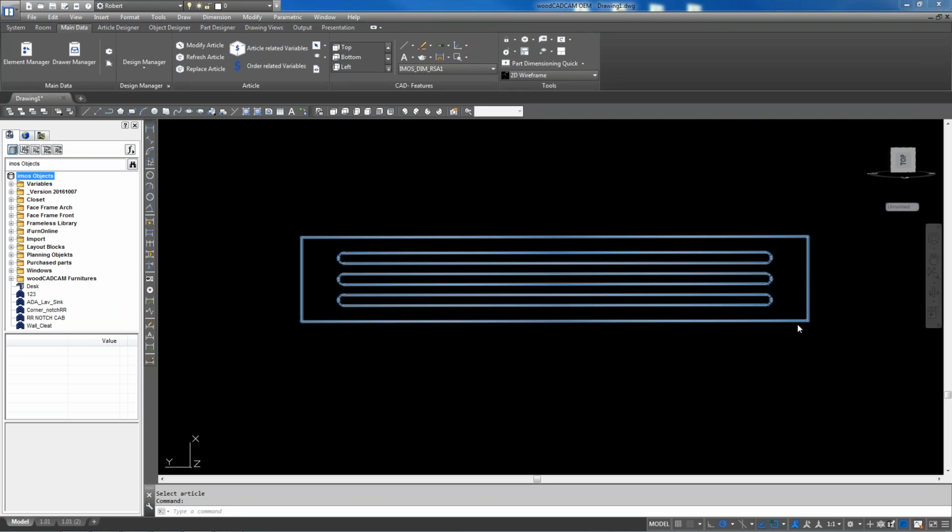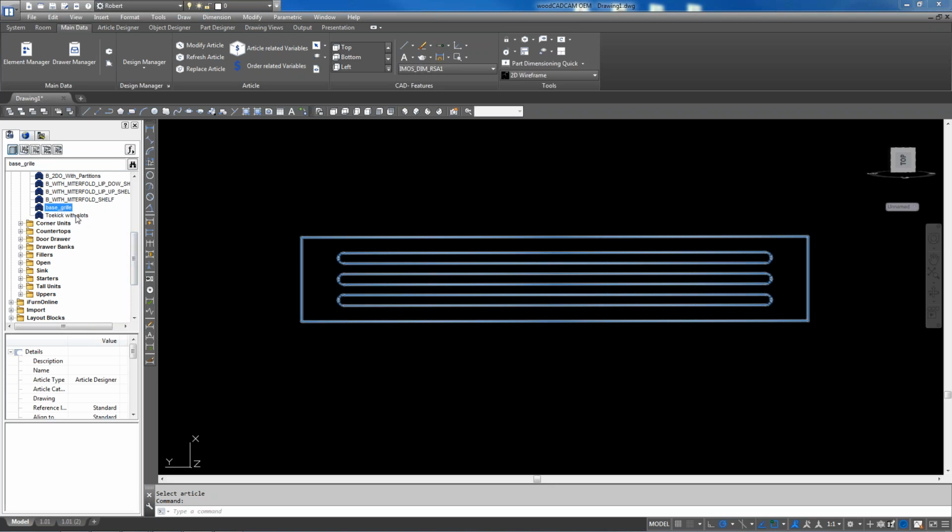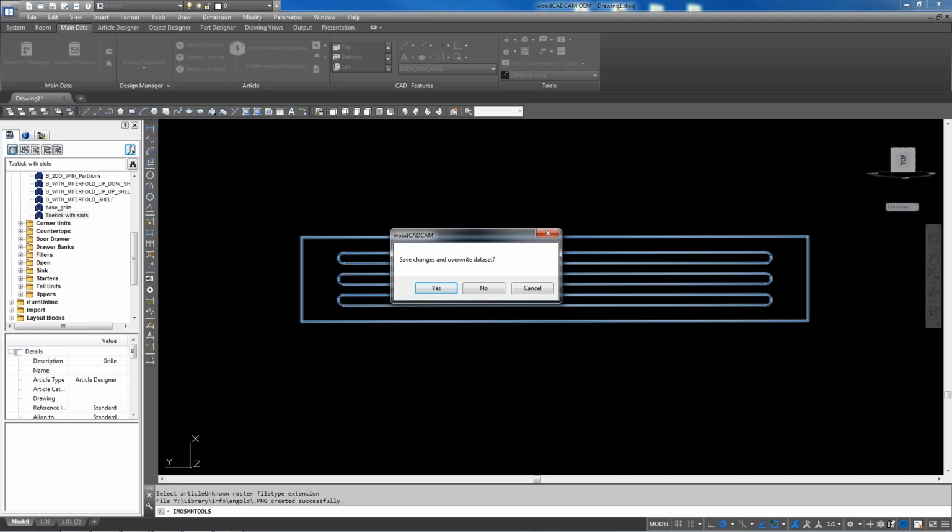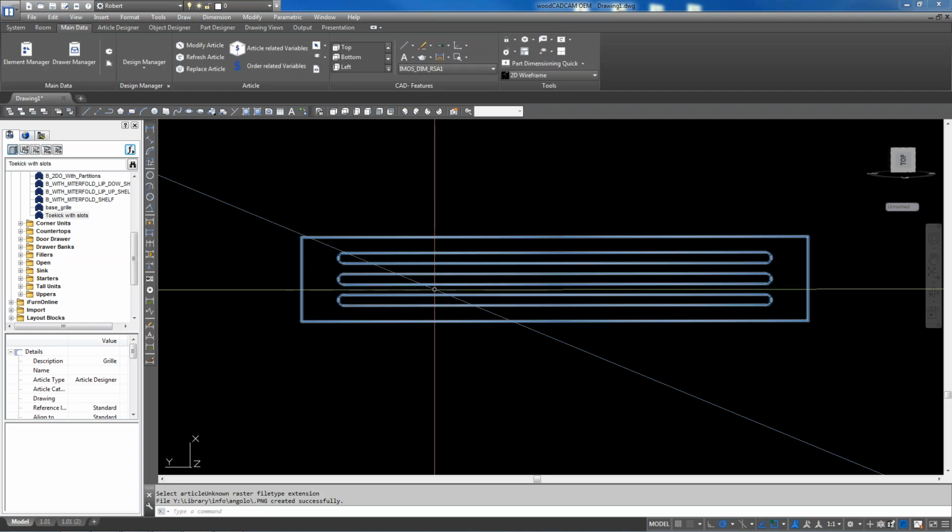Okay. Do you remember how to make a preview picture so it shows up over here? Preview picture. Yeah. So when you select this guy, okay, what's what you call it? So you get a little picture of it down here. So select it from your list and say select preview. There's my preview.